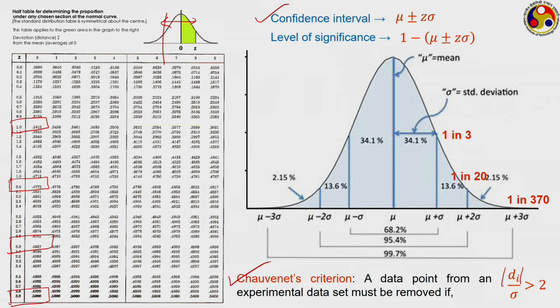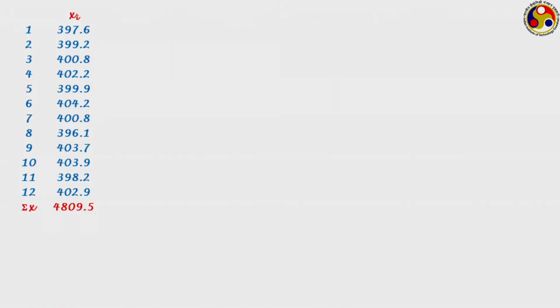we know that 95% of the data should have d upon sigma less than 2, but only 5% data can show this kind of criterion and we should discard them, thereby causing a change in both your value of x mean and your corresponding sample standard deviation, and thereby providing a much better measurement. Here we take a sample like that pressure measurement example that I have mentioned about.